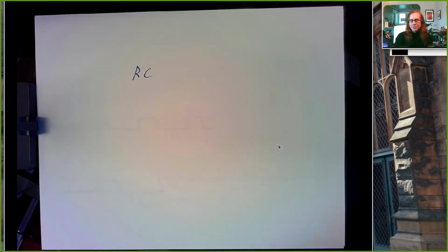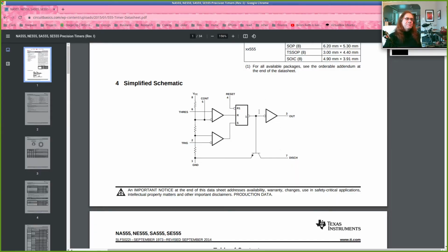And with a single resistor and a single capacitor, you can make a pretty simple circuit that, if you analyze it, you'll find the output changes over time. It comes out as some kind of sinusoidal function. And with a 555, we run the output through a digital device, which will basically change the output to be either high or low. So it would take a sinusoidal output, turn it into that rectangular wave.